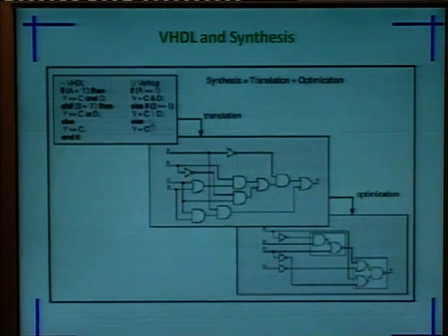First, let us see which type of code is preferable for our design: either behavioral or structural. In behavioral modeling we use the process statement, which is sequential in simulation, so it may not be useful for high-speed applications. For high-speed applications we have to go for structural modeling, but at the cost of power. In behavioral modeling, power consumption and dissipation will be less as compared to structural.